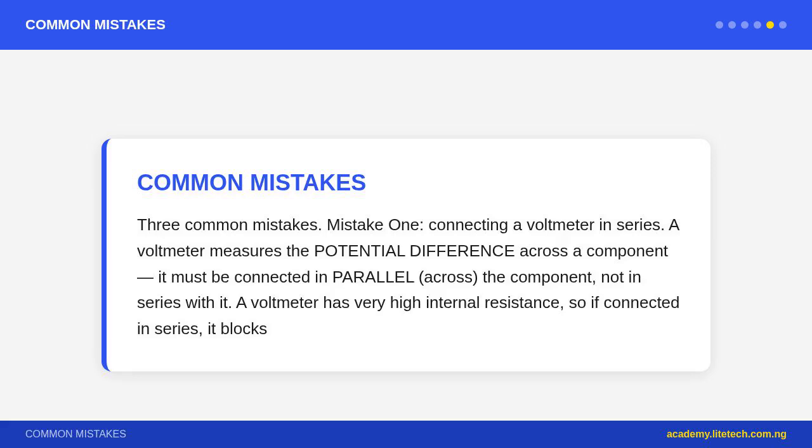Mistake 2. Replacing a blown fuse with a higher rated fuse because it won't blow again. The fuse blew for a reason: there was excessive current. Fitting a higher rated fuse means the underlying fault, a short circuit or overloaded cable, is not protected. The wiring could overheat and cause a fire before the new fuse blows. Always investigate why a fuse blew before replacing it.